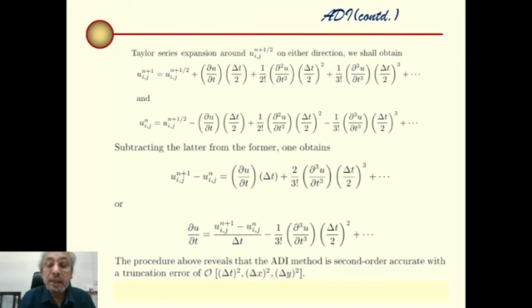So eventually we have reached second order accuracy of discretization in the time direction. So the alternate direction implicit scheme is not only second order accurate in space but also second order accurate in time. So we have learned through this the explicit formulation, implicit formulation, simple Crank-Nicolson implicit scheme, and the alternate direction implicit scheme, which is ADI with higher order accuracy in the temporal direction as well.